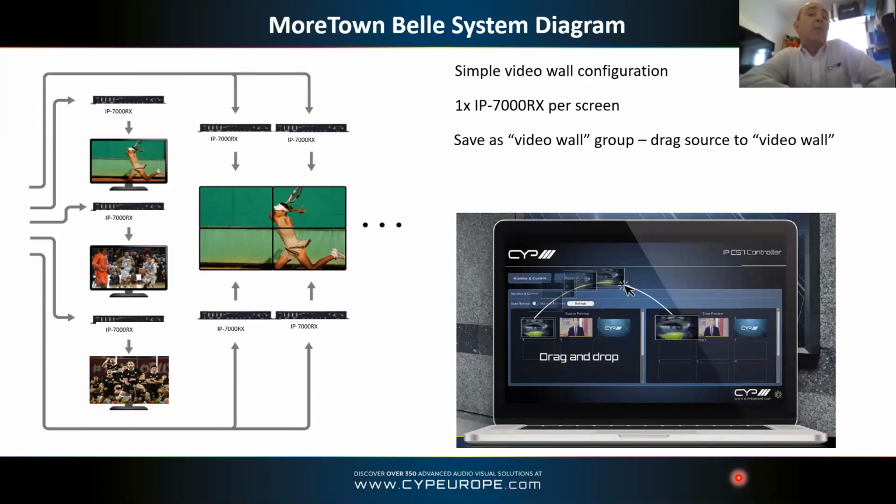Yeah, exactly. And I guess one of the most useful things there is actually you can still use the 4 screens independently if you want. So you've got one on your zone preview area there. You'll have one that will give you an icon of a video wall where you've named main video wall or video wall over bar or wherever your video wall is, so you know which one you're talking about. But also later down in the list, and you can change the order of this list as well, you can make whatever you think is the most important stuff appear at the top, and the other stuff that's not important appear at the bottom. So you can still actually drag and drop a signal to an individual screen within that, and almost create a multi-view with it. It's not really a multi-view, it's slightly cheating, but almost.